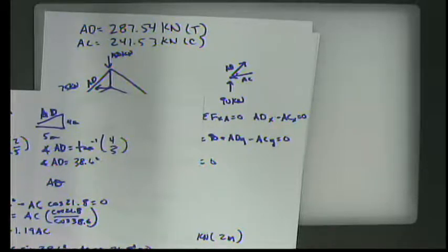Right. Super. So then, can you explain why if we only have 150 kilonewtons down, those forces are so great on those two members? Well, it just can happen. You just distribute it. Tension and compression are opposite in sign. We also have that 75 kilonewton force. So it's distributed in an odd way. And the 75 really pulls it off, because if you think about it, A can't bear any of it, can it? Because it's horizontal. So you're going to be putting that somewhere else on that truss.